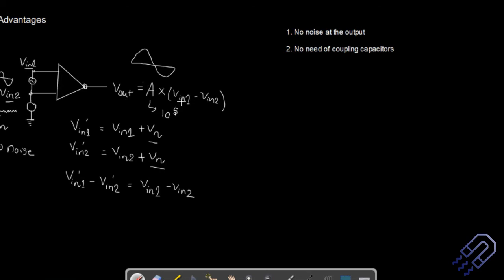No, that is not possible. There are some restrictions with that. We're basically going to amplify a signal which is very weak, might be 1 milliampere, 1 microampere. Those kinds of signals can be amplified. So when you do any kind of experimental studies and you get a very weak signal and you want to know the effect of that signal, you first need to amplify it to study it. So for amplifying such signals, we can use something like a differential amplifier.